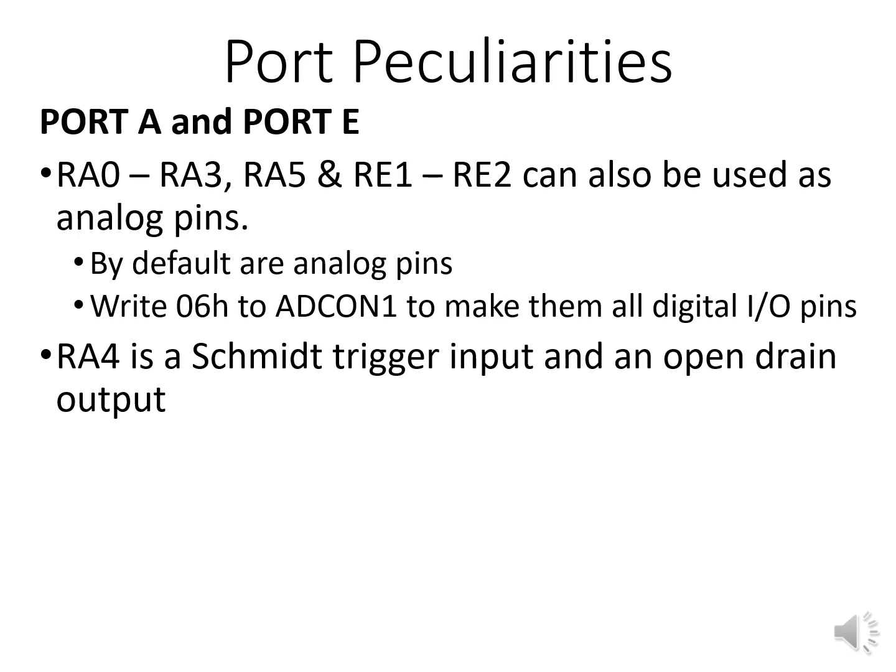To do this, for the time being, we will write the value 06H to the SFR ADCON1. Details on how to select values to write to this register shall be covered when we go into the topic about analog to digital conversion on the